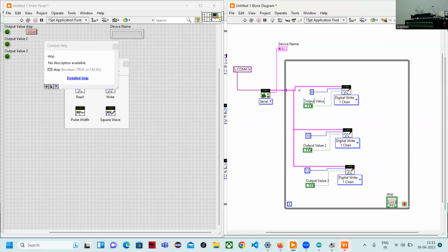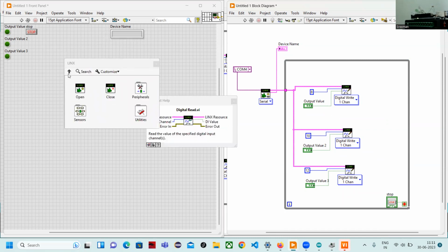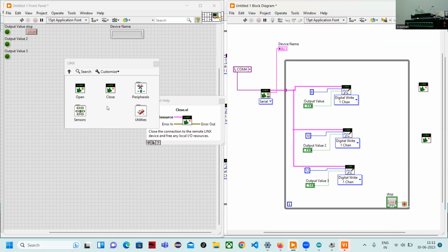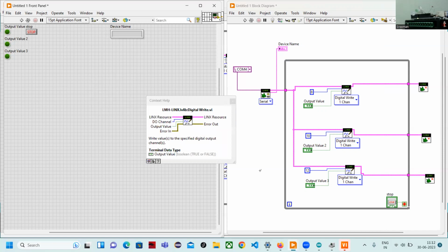And after this, we have to terminate the connection as well. Here I'm showing only how we can turn on and turn off an external LED through LabVIEW, with the LEDs connected to the Arduino board, right? So I have to terminate each connection, which can be closed out here. The close button. So all of them are closed, and you can see that our program is ready.